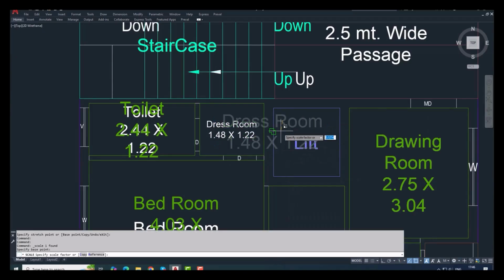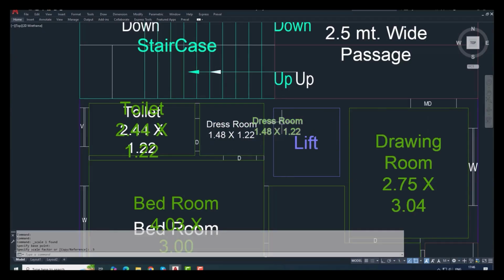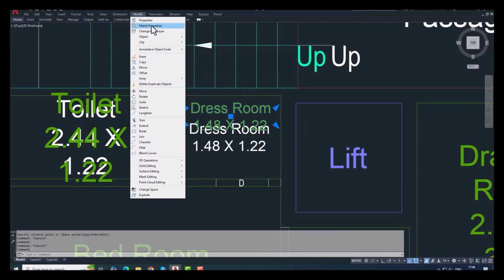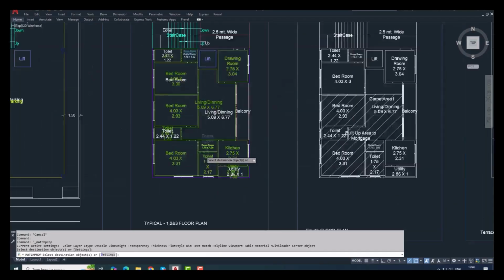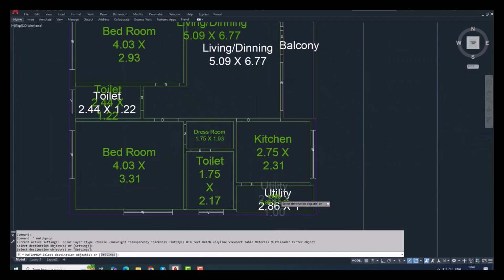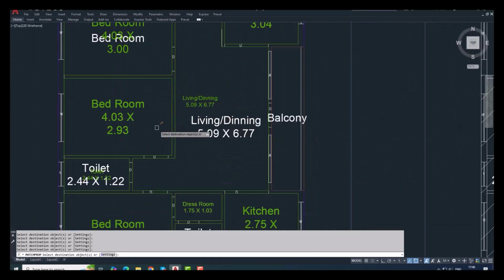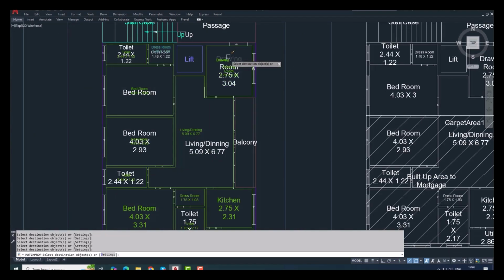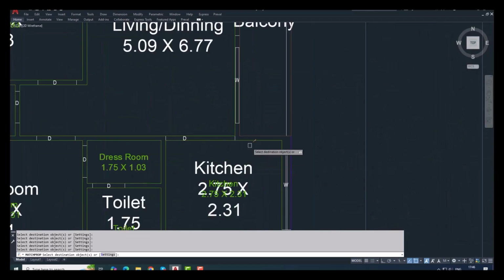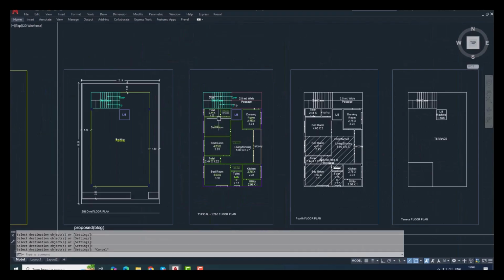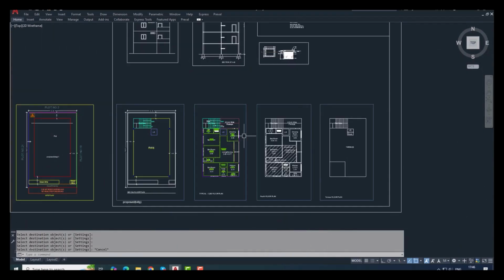Make sure that all the labels are scaled according to the size of the room or have been made sure that all the properties have been matched accordingly. Also, remember that all the arrows of all the labels in each room have to be inside the designated polygon. The arrows is what determines the boundary of the room.